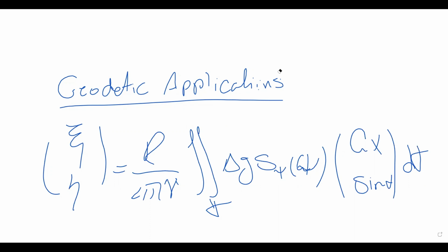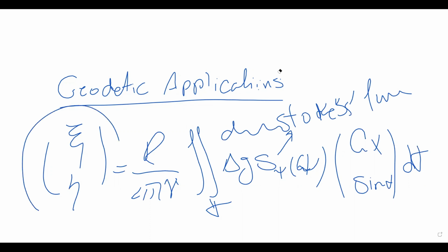Which is the Stokes function, and this is the derivative of the Stokes function actually. So this part, if we have gravity anomaly, we can compute that, but we do not have the gravity anomaly. We have the geoid. What can we do with that?